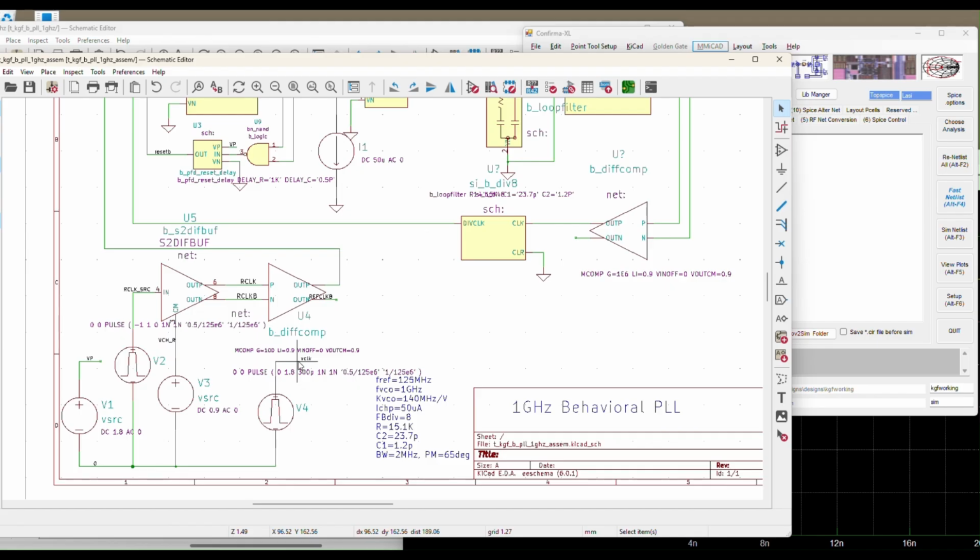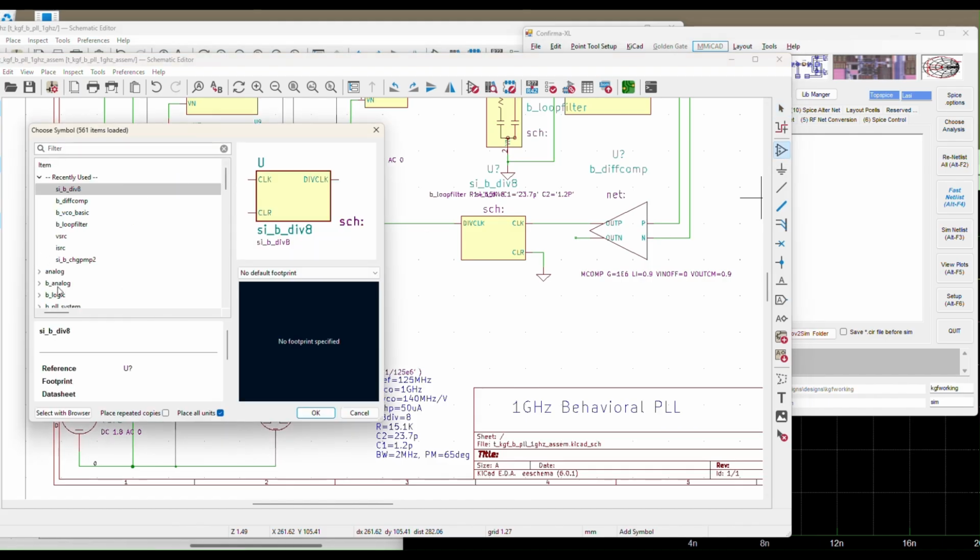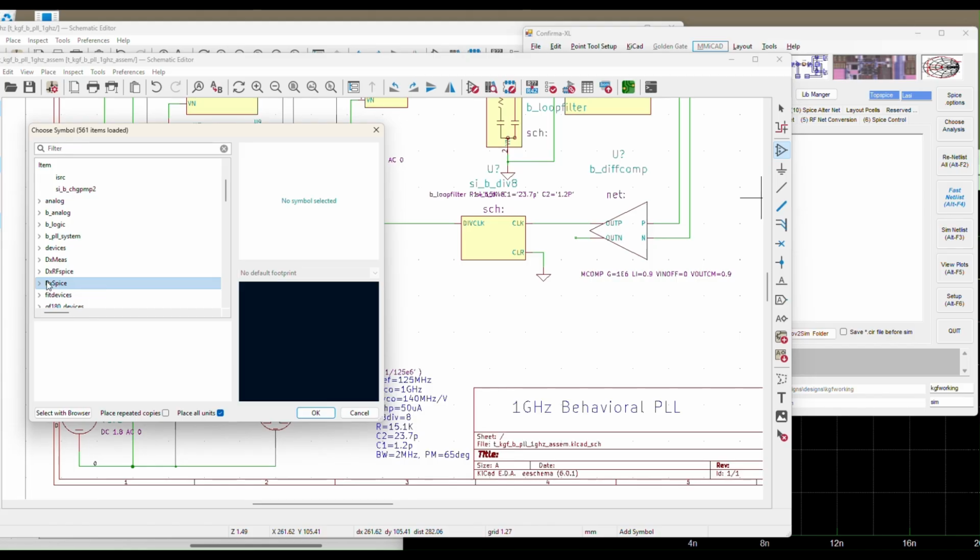Sometimes if you have an unconnected voltage source like this, an independent voltage source, Spice inserts a resistor so you don't have a node floating. But not all Spices do that, and I don't remember with TopSpice. So we're going to add a resistor just to be safe here. So let me go to DXSpice and expand on that. Let me grab a resistor.